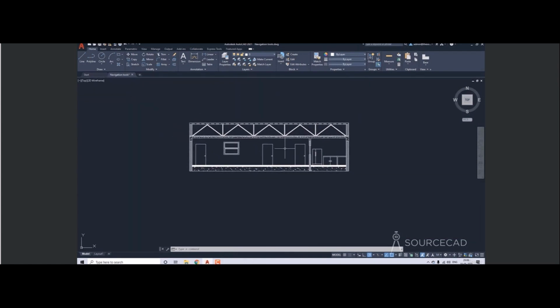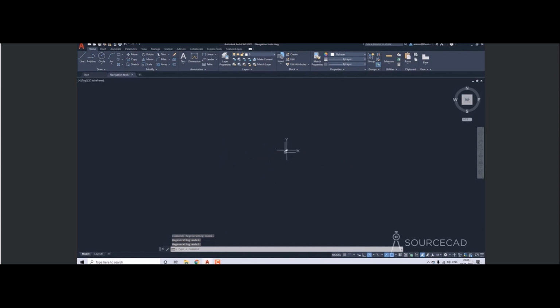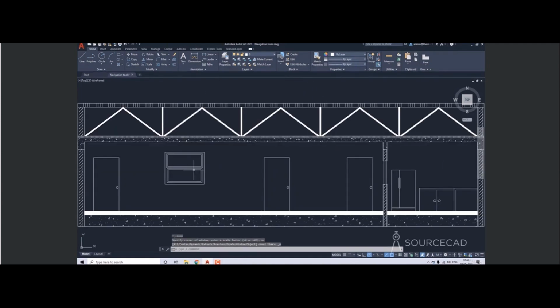Now there is a zoom tool which you might end up using quite frequently, and that tool is called zoom extents. Now you can use zoom extents for situations like these. When you have a drawing which is really very small, or maybe if you've made something and it's really large, it's not even visible in your drawing area, then you can fit your drawing simply by double clicking your mouse wheel, and this function is called zoom extents. So I'll double click my mouse wheel, and here it is. It will zoom your drawing and it will fit it in the visible drawing area.